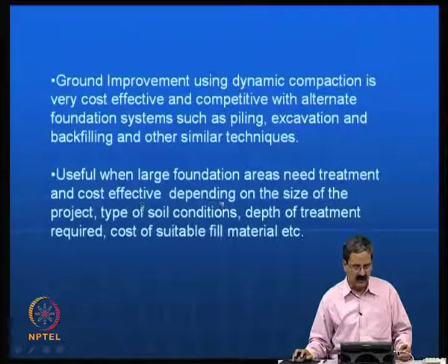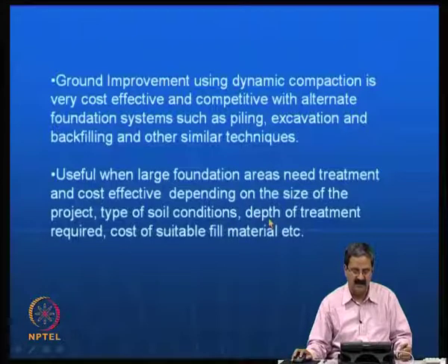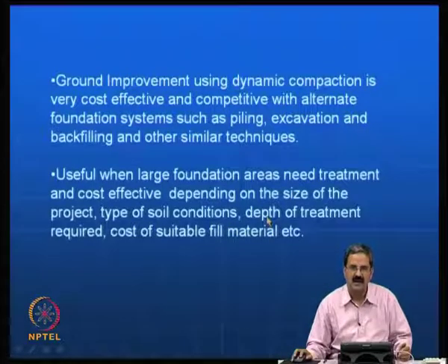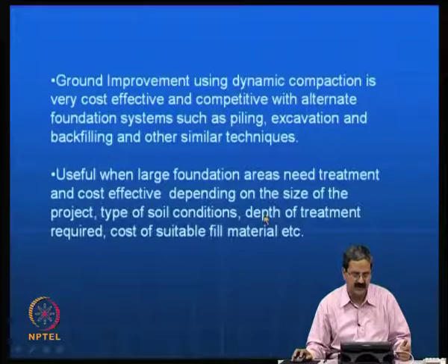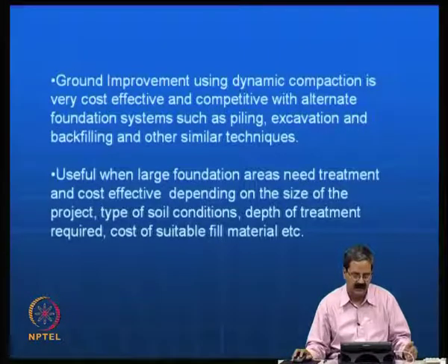They result in cost effective solutions, because it depends on the size of the project and the type of soil conditions. For example, as I just mentioned, the techniques of dynamic compaction have quite a big range, right from municipal solid waste to sands it can take care of, and the cost of suitable fill material is also important.